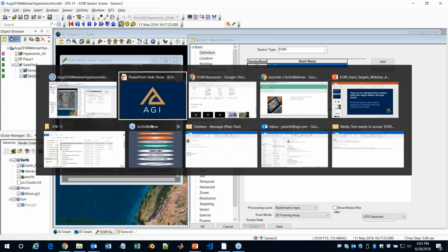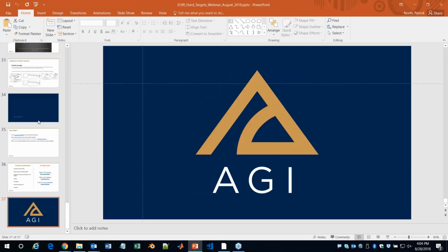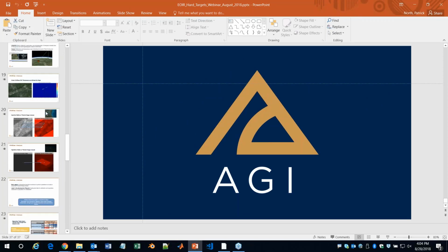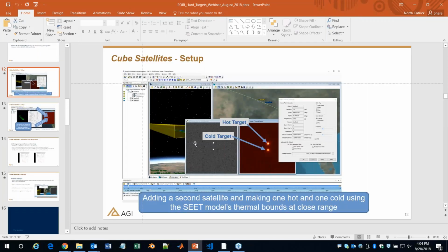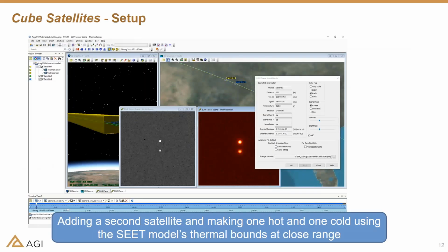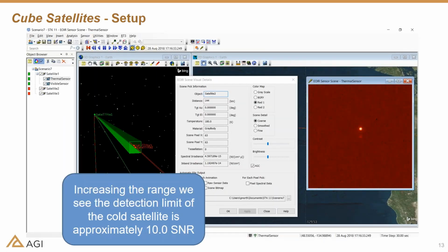So in the examples that we showed much earlier in the slides, when we jumped from, I think it was like 120 to 140 kilometers, the fall off is just that distance squared effect where you're jumping pretty far away relatively. So that's where you're going to start to see that dimmer target fade, and that's because you're hitting the noise floor. So they're both going down proportionately, but the difference is that one's going below the noise floor and the other's still above it.